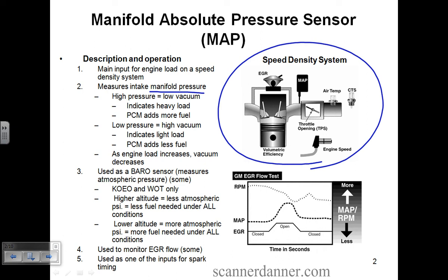With the MAP sensor being the critical player, and I missed this part, I'm not talking about an engine with a mass airflow sensor. We just have a MAP. Okay? The MAP is really the most important sensor we've talked about so far. More important than engine coolant, more important than throttle angle, more important, of course, than the intake air. This MAP sensor is used pretty much all the time as far as how much air is entering this engine.